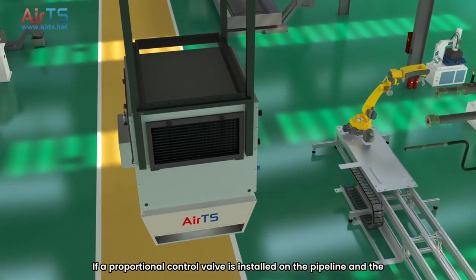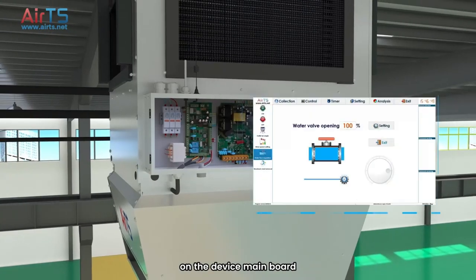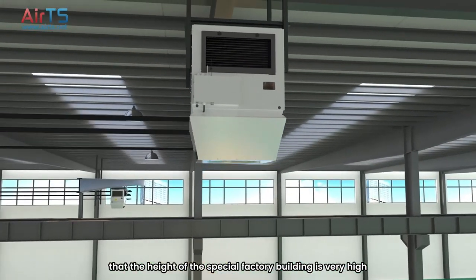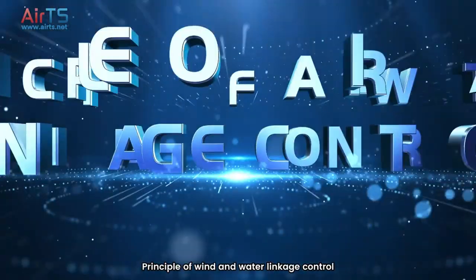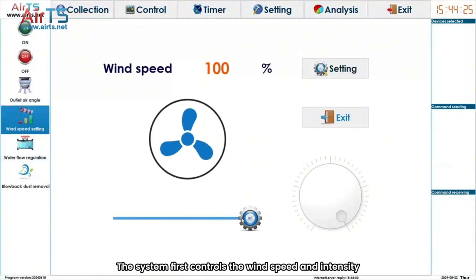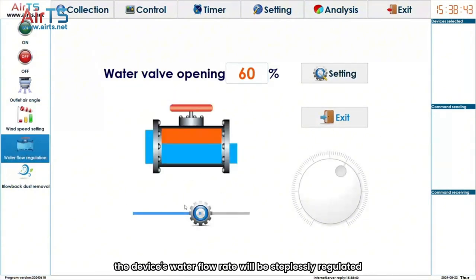If a proportional control valve is installed on the pipeline and the control line is connected to the reserve port on the device mainboard, the water supply flow of the device can be continuously adjusted to solve the problem that the height of the special factory building is very high and the wind speed cannot be adjusted too low. Principle of wind and water linkage control: the wind speed and intensity adjustment range can be set in the system. The system first controls the wind speed and intensity. If a satisfactory value is not reached within the setting range, the device's water flow rate will be steplessly regulated.